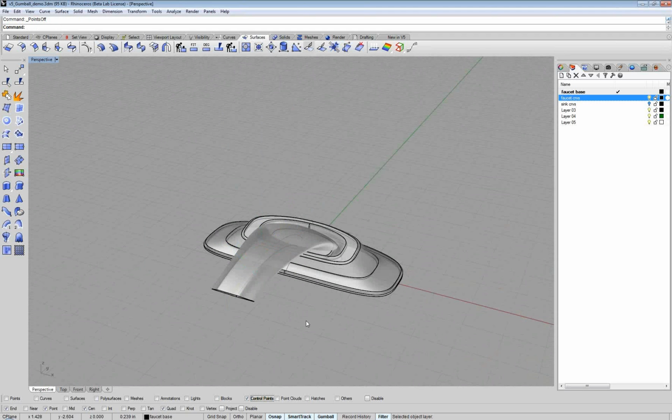And one thing that I'll encourage you to always remember is that if you use selection filters, remember that you have them on. It's easy to forget that you have them on, so if you then try and select something like a curve or a surface, you won't be able to. It's because your selection filters are still limited to control points. So the fastest way to get back to the default of being able to select anything in the scene is to right-click over the one object type selected and then immediately left-click. So that was just right-click and left-click, and I'm back to my defaults.